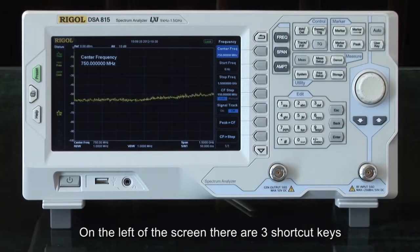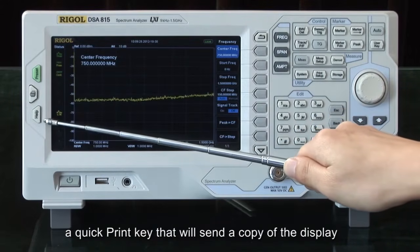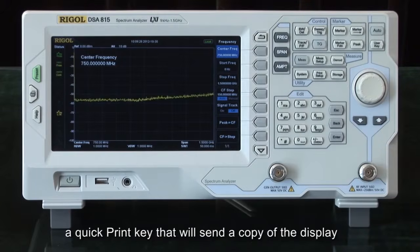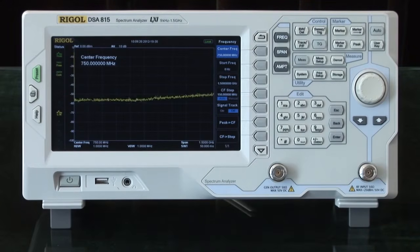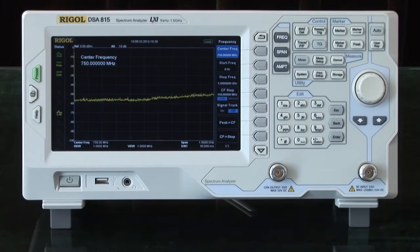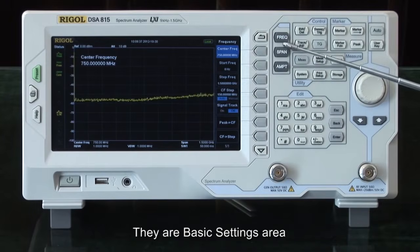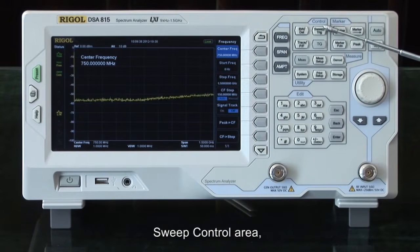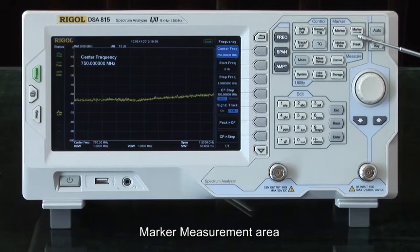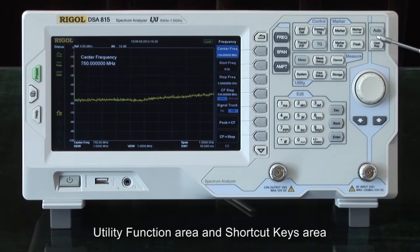On the left of the screen, there are 3 shortcut keys: a preset key that can recall a user setup, a quick print key that will send a copy of the display to an external USB memory stick, and a help key. On the right of the display, we have a series of operation menu keys. The function keys on the front panel can be divided into 6 areas. They are the basic settings area, sweep control, marker measurement, advanced measurement, utility function, and shortcut keys.